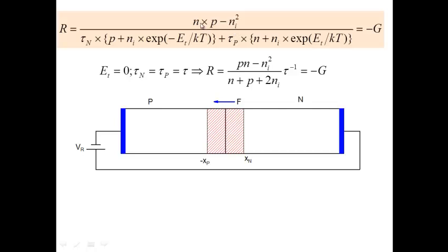And note, if you look at this recombination, we have two terms here. We have np and ni squared. n into p, the first term, describes recombination. The second term, minus ni squared, describes generation. In equilibrium, we know np equals ni squared. Recombination balances generation. Okay, so either I can write recombination like this.